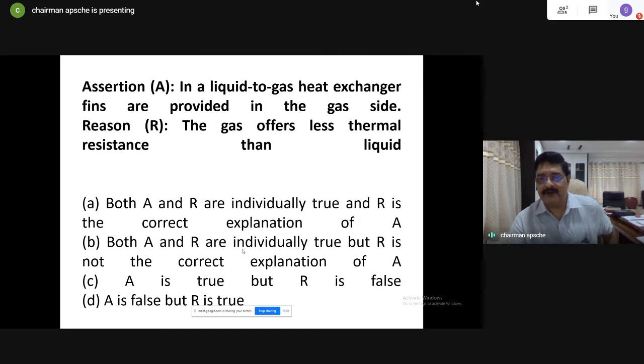Now, a similar device with a dynamic response. I told you, the temperature of the fluid continuously changes in many mechanical engineering applications. When fluid temperature is changing very quickly, from millisecond to millisecond, your thermocouple should be in a position to measure the temperature. The principle of measuring temperature using a thermocouple, as I explained yesterday, is the Seebeck effect. The temperature difference causes an EMF to be induced in the circuit, and the EMF is calibrated to record your temperature.